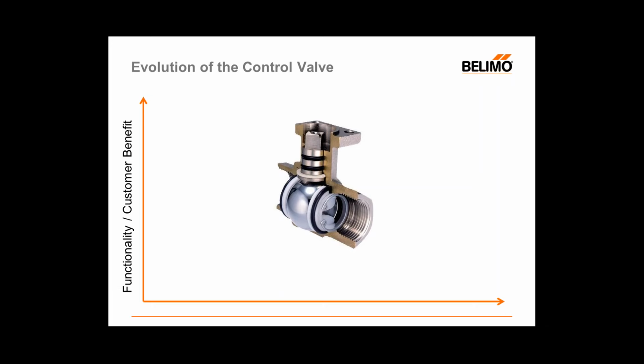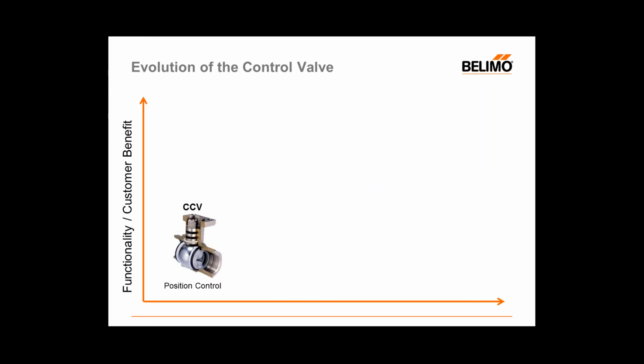And really, with a pressure-dependent valve, just as the title says, pressure dependent, we're dependent on how much pressure is applied to the water going through that size opening to determine how much flow actually comes through that orifice. So that was the technology for a really long time, but it's arguable as to when the first PI valve was really used, but we'll call it not so long ago, pressure-independent valves were created and introduced into commercial HVAC systems.